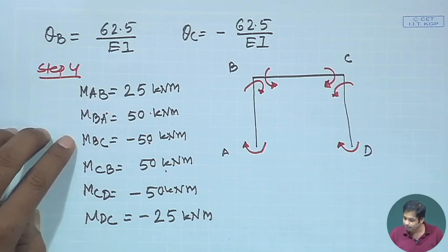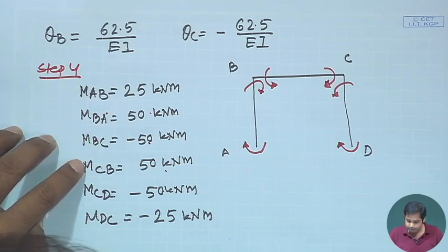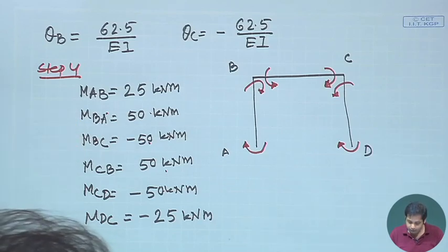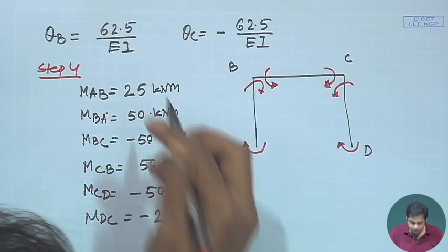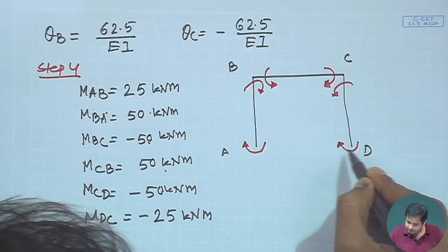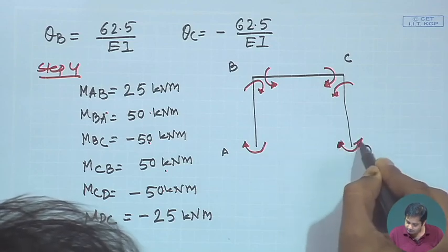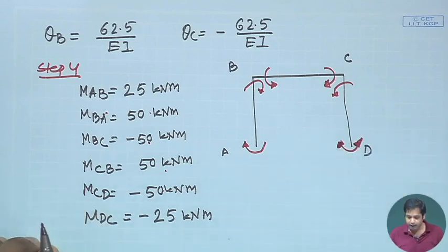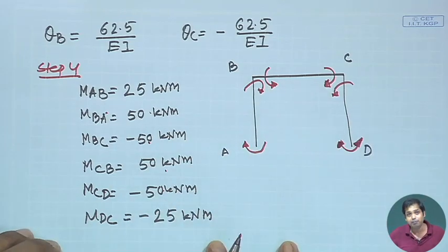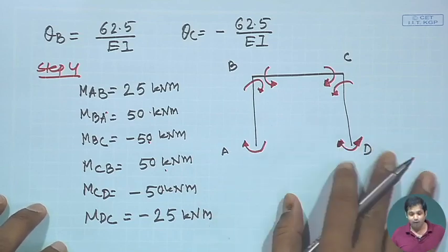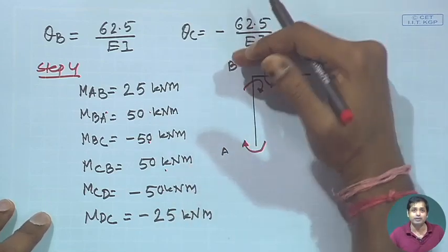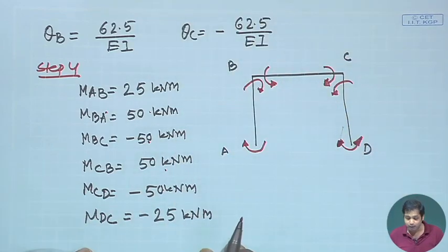Okay, fine. So, now this is clockwise and this is clockwise, and this is anti-clockwise, and this becomes clockwise, this is anti, this is like this. Now, these are the bending moments. When we draw the bending moment diagram, we need to see whether they are hogging moment or sagging moment, or when the bending moments are drawn on the compression side, at least as per our sign convention.